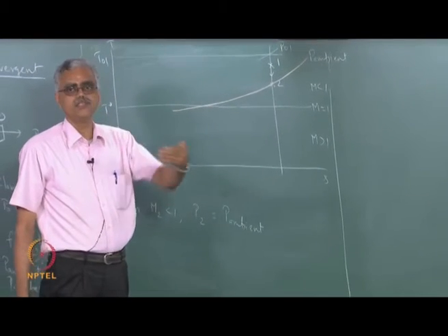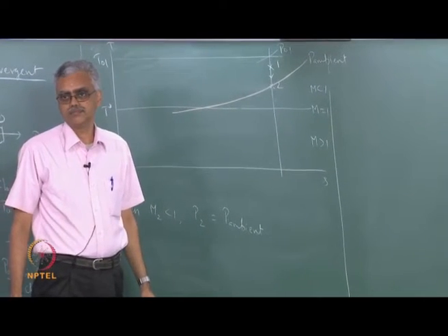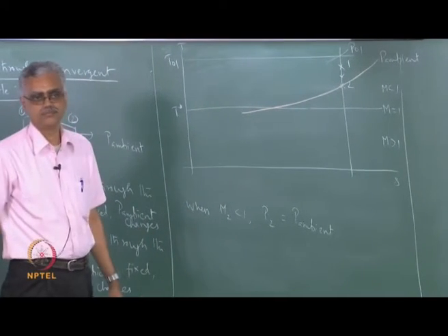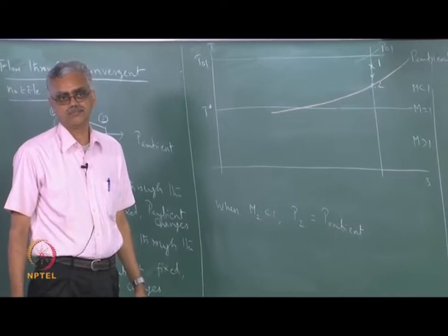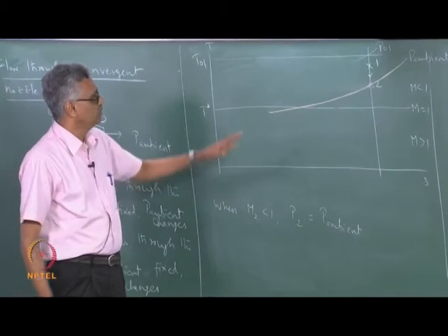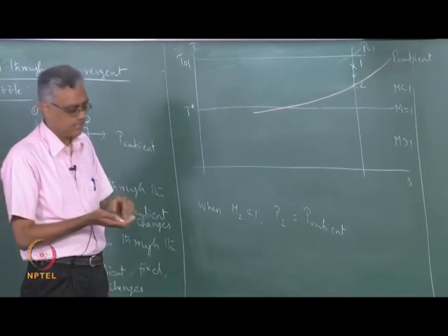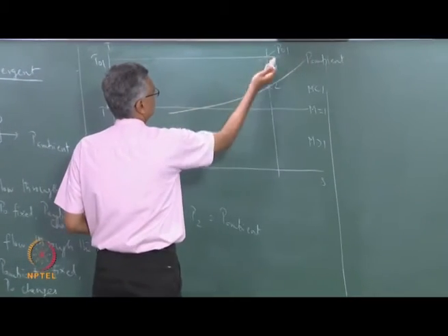Now, I increase the stagnation pressure. What happens to the inlet state? Where do I show it? Remember, isobars diverge from each other. So when I increase the stagnation pressure, I need to move to the left.